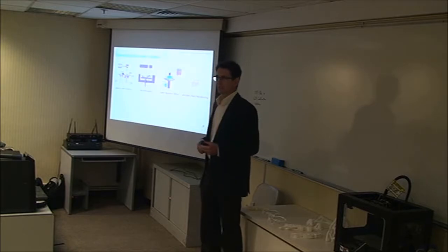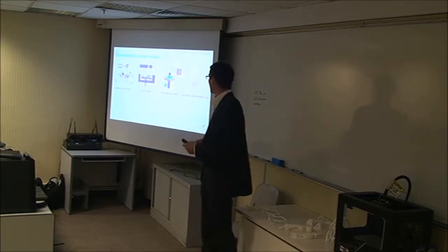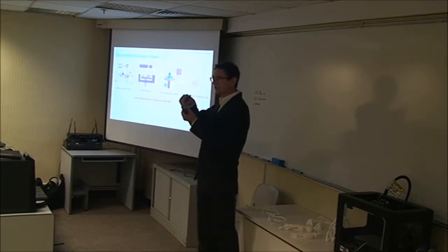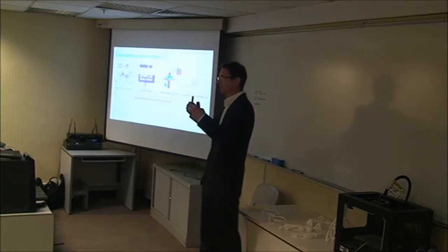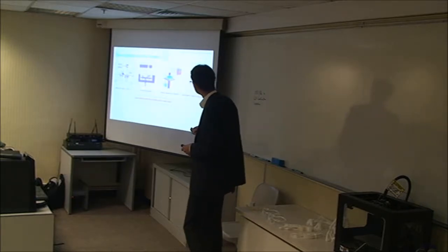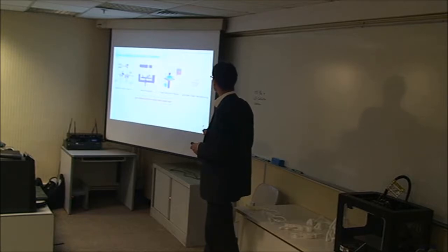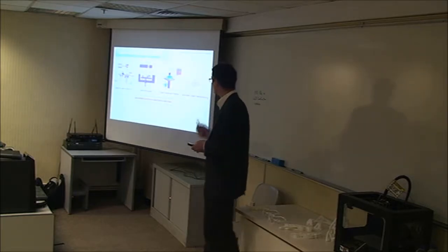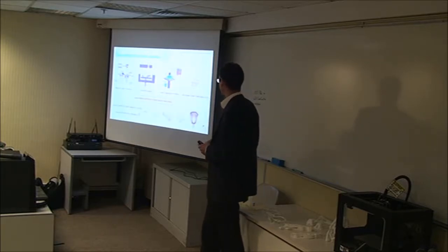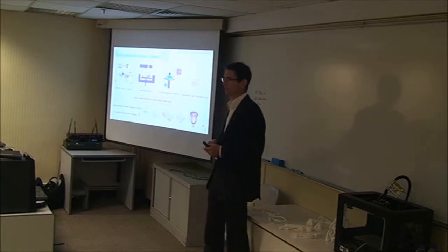There are a lot of methods you can use. I saw that down there in the lobby, there are a lot of printing machines standing, different methods, but all of them have one thing in common. You place material, liquid, or whatever material it is, next to each other, and you try to combine them. Different ways: with a laser, with ultraviolet light, here you melt it, and here you have laminates, and you bring them together. Different methods, but one in common: you add material step by step to the other ones, and that gives you the freedom in the design.